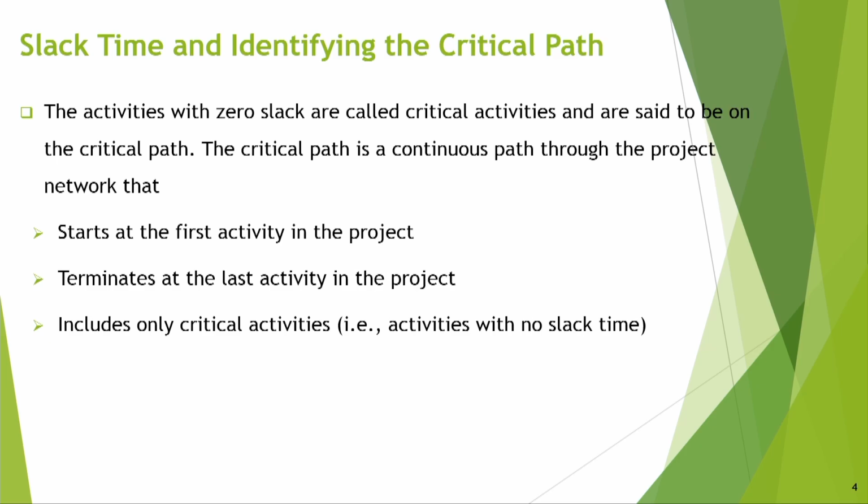The activities with zero slack are called critical activities. I have already told you what the characteristic of that will be. Of course, latest finish will be latest start plus duration. If you follow the activity in this style, and it is on the critical path, then 3 conditions are to be met.